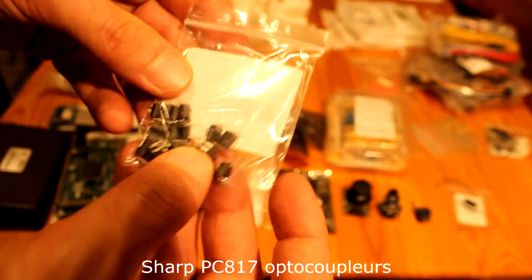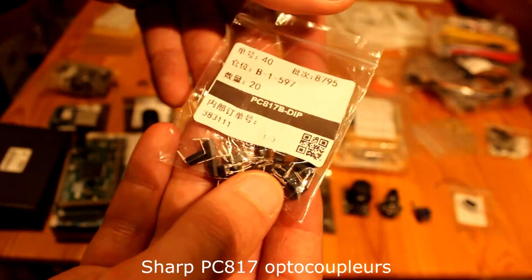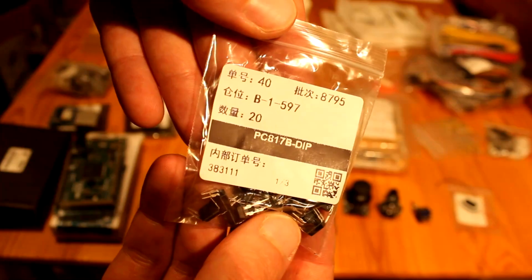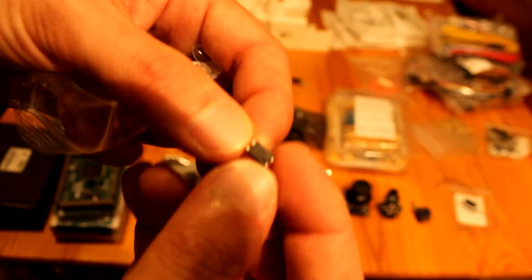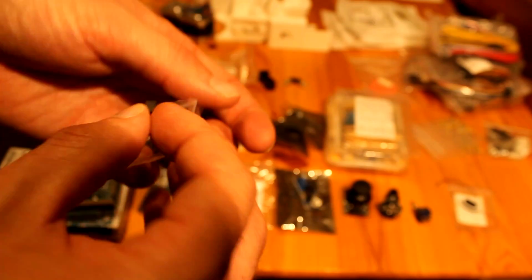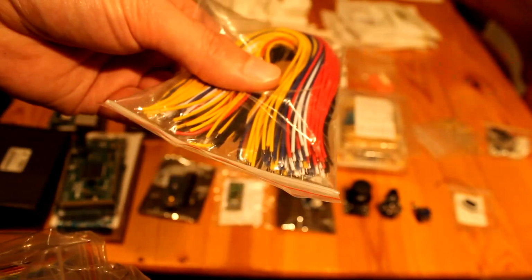Here we have the PC817 optocouplers. These are used to electrically separate 2 circuits. We use that for the auto-guiding part, so we can separate the Arduino Due and the Arduino Nano. We use one component for one wire of the auto-guiding, so it's more secure to not damage one or the other.